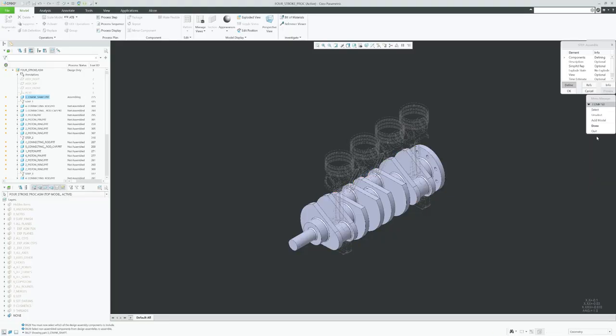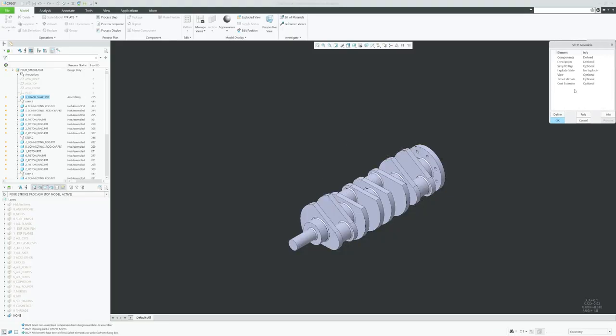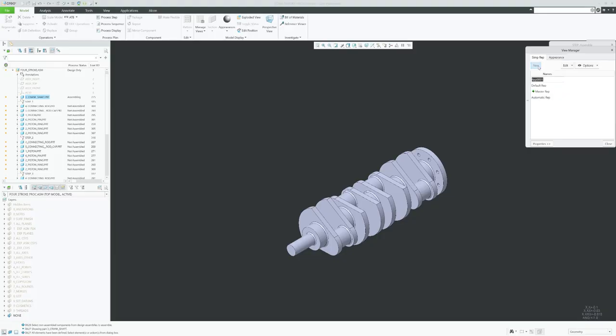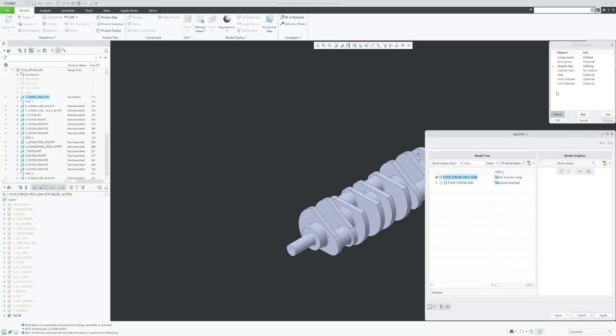Click OK, done. And we have some parameters up here that will show you the simplified representation, which is the part that will be activated in a certain step. So in this particular one, we can create a new simplified representation and call it step underscore 1, like this.